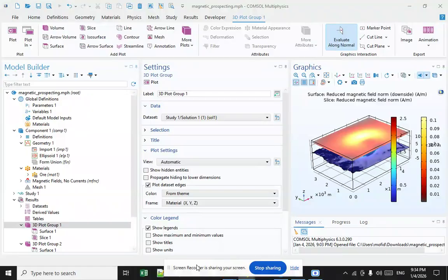Flux gate magnetometers utilize two ferromagnetic cores, each wound with a primary coil in opposite directions and an outer secondary coil attached to an ammeter. When an alternating current (AC) is passed through the primary coils, it creates two opposing magnetic fields that vary in intensity based on the outside magnetic fields. By floating them parallel to the seafloor, they can measure the changes in the magnetic fields over the seabed.